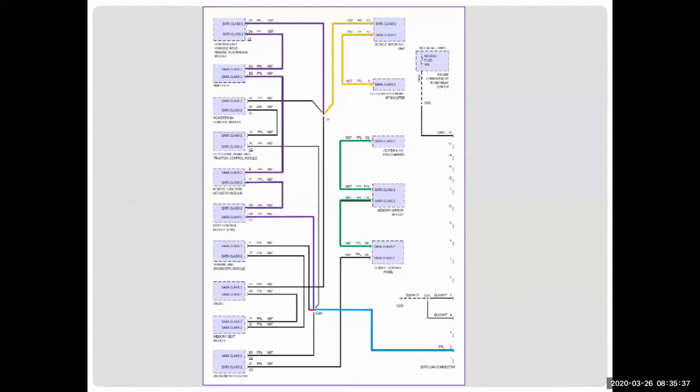Yeah. If we're testing a module and the module is bad, the only thing to do is to replace it, right? You can't fix modules. Correct. I'm going to hesitate on that. There are shops and places that do fix some of the modules. Sometimes it's just an analog to digital converter or a transistor that's gone bad or a driver. But there you're moving from auto repair, which we do, into electronics. So in the field, all we do is replace modules. We don't repair them. But there are rebuilders out there.